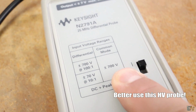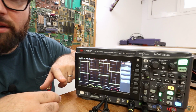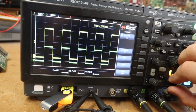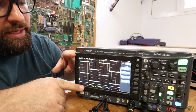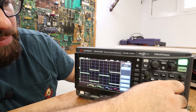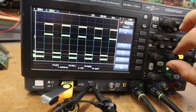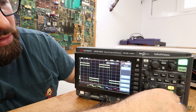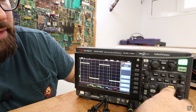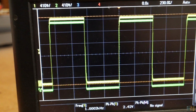Another thing that a lot of people do when measuring two or more signals is placing one signal on the upper side and another signal on the bottom side in order to see them at the same time. But that's a bit wrong, because the more space you occupy on the screen, the better the ADC will work, because it will use the entire range of the screen. So basically what you want to do is go to channel 1 and make it as big as possible, so it occupies the entire screen. Then go to the second channel and also make it occupy the entire screen. And if you want, you can just move them around, or activate one at a time and then activate the other one at a different time. Because otherwise you'll just use a small part of your ADC.